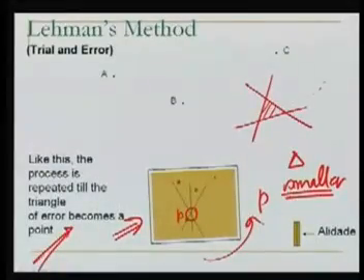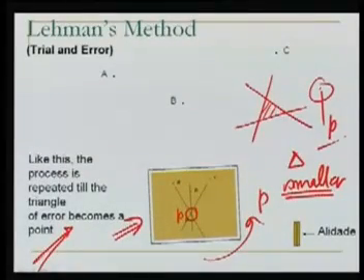So this is what we have achieved in this case. Once this triangle of error becomes a point or very small, this point is small p, as well as our table is also oriented. So we have found our solution. We have done the orientation and resection. Now we are ready to plot. So we have now seen some methods using which we can do the resection.